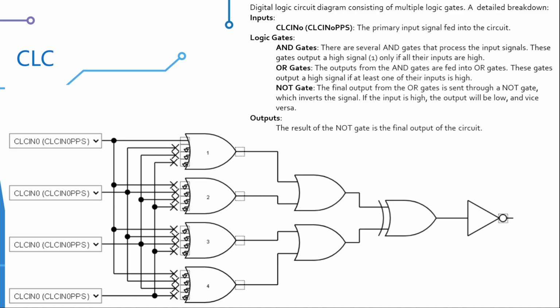Because what we're going to do, using a digital logic diagram like this, is create an input, use some gates, and then invert the output. And it'll make sense to you in a moment, because I'm going to do the following. Put my pen on. I'm going to set the PPS of the switch as an input to here. It will come through here, and then I'm going to invert the output here. So when I push the button, LEDs will come on. How do we do that?